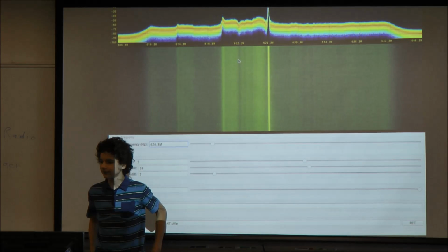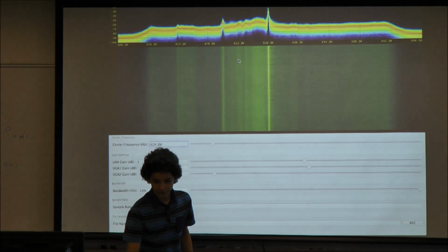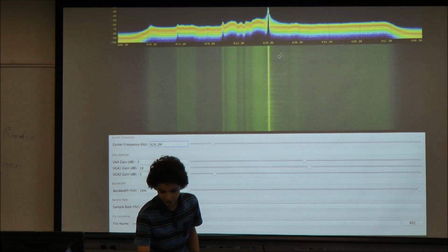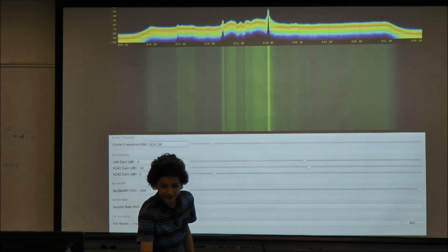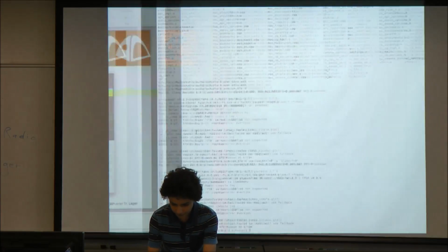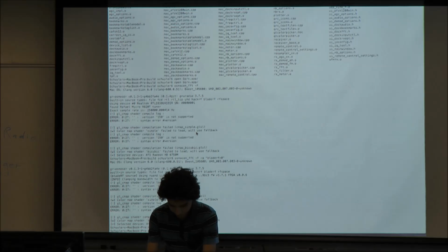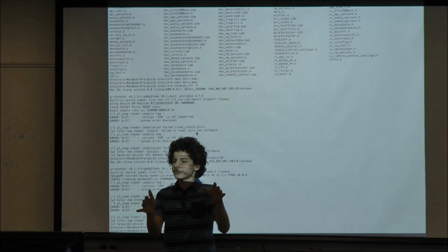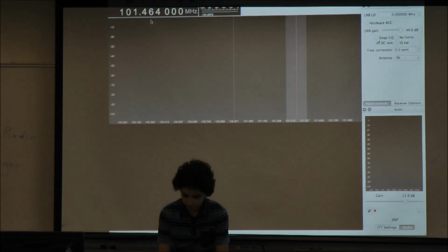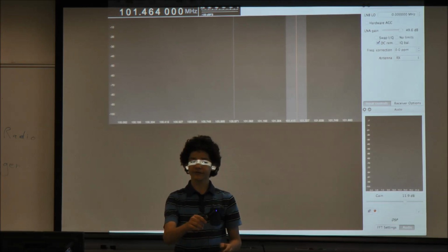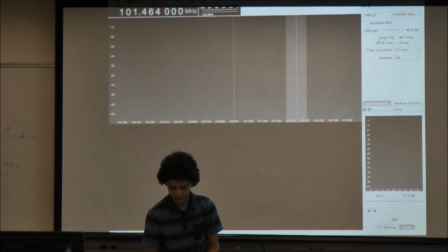Yeah. So right now here's my voice, and as I talk you'll see it. This is FM. We can actually receive this. So if we go back to GQRX here, so if we open GQRX. GQRX is nice because you don't need to do anything with a flow graph, and in this case I'm using the RTL-SDR because 626 megahertz is within its frequency range.